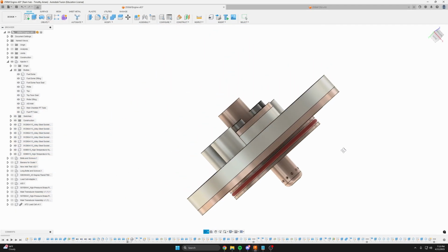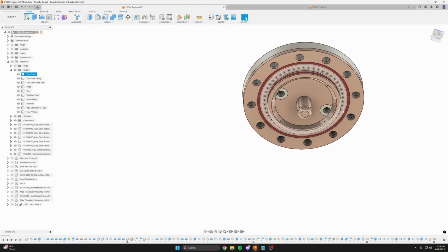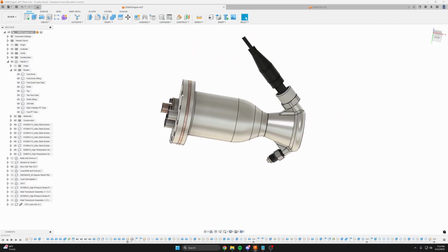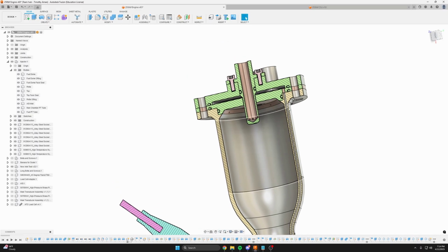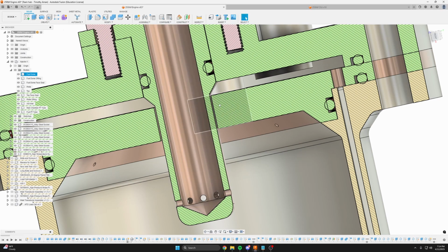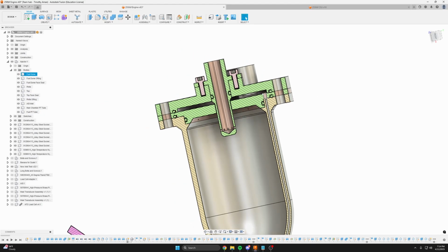Another thing to consider with Pintle injectors is whether you have a fuel-centered or aux-centered Pintle. In our case, we chose aux-centered simply for ease of manufacturing, because our fuel is already flowing up through the cooling channels, so it sort of flows up the cooling channels and then goes through these holes, and it's already here above the fuel dome, so it's much easier to just inject it through the annulus gap than it would be. We'd have to pull out the propellant and inject it back through the Pintle tip if we wanted to do a fuel-centered Pintle. So it's much easier to just do an aux-centered Pintle since our fuel is already being used for regenerative cooling.